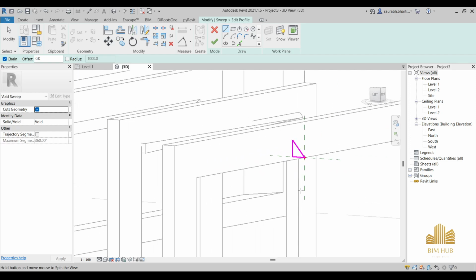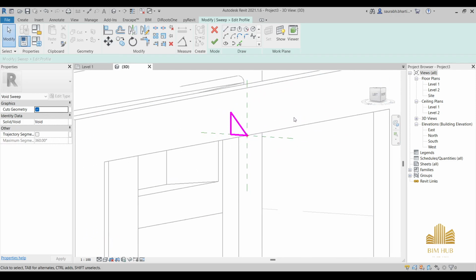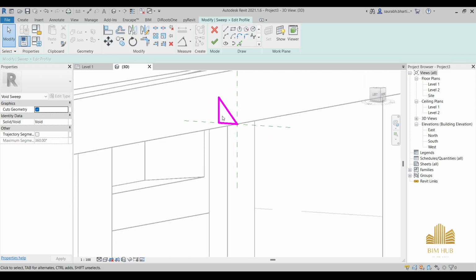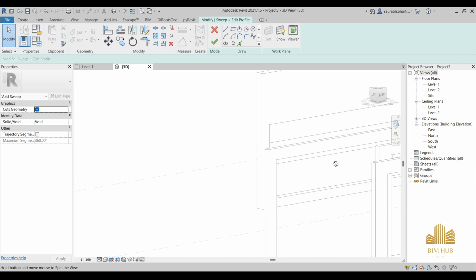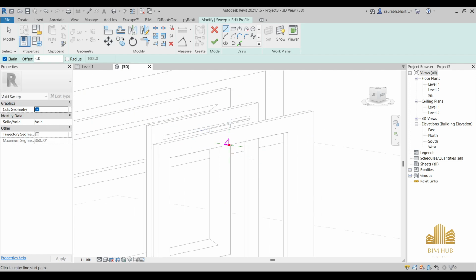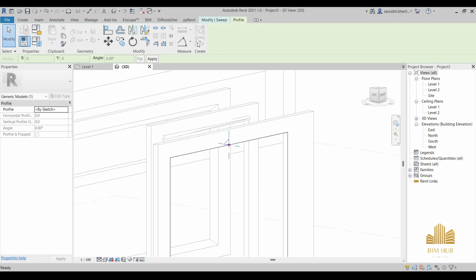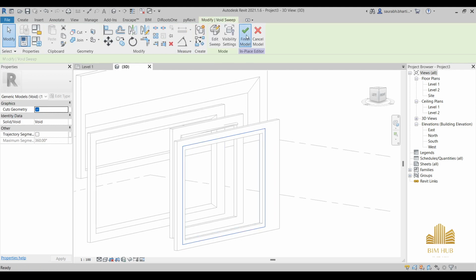What it is gonna do is cut all over this place at an angle. As you can see, I have made it from the front side. Yeah, the angle is wrong. So to make the angle over here, we have to draw the angle something like this and this. And now you can just finish it and go to Modify Sweep, finish, and finish.